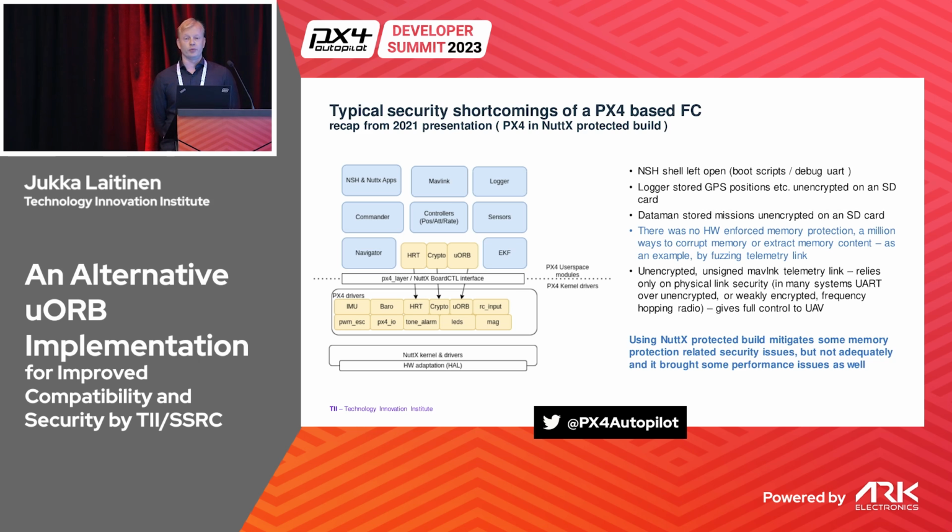We have been working with many security things inside PX4, and many of those things are sort of easy to solve or require some basic engineering. Like when you are making a product, you can always close extra debug interfaces from your product, and you can store data in encrypted format instead of unencrypted plain text on your memory cards. And we actually implemented some interfaces and upstreamed those to PX4 for that purpose back then.